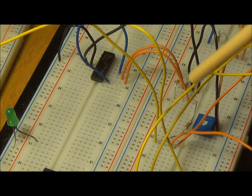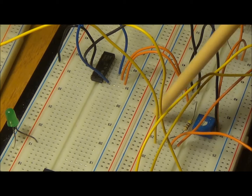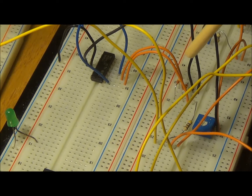The reduced voltage is now fed to an operational amplifier. It's here, and through a current limiting resistor, this goes to the inverting input. The non-inverting input is grounded, and I also have two clamping diodes between the inverting and the non-inverting inputs. Their function is to clamp the voltage levels to plus 0.7 volts or minus 0.7 volts. That's to prevent excessive voltage at the input and to prevent any damage to the operational amplifier.